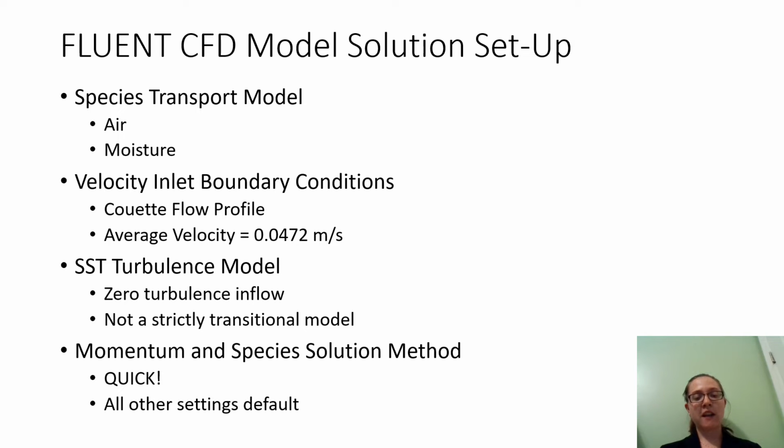Our velocity inlet boundary conditions were set to be a Couette flow profile using a UDF, and our average velocity was set to be 0.0472 meters per second.